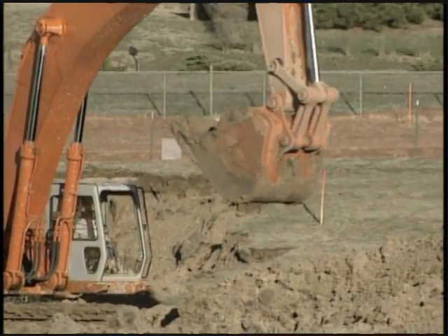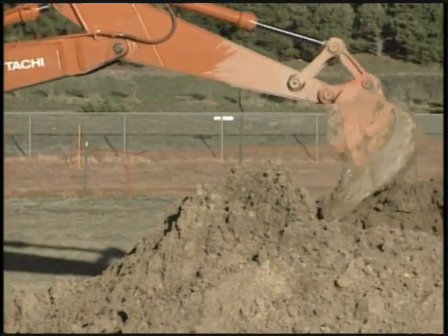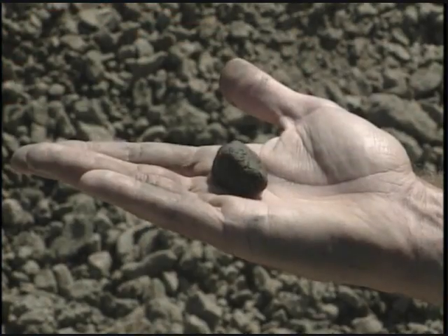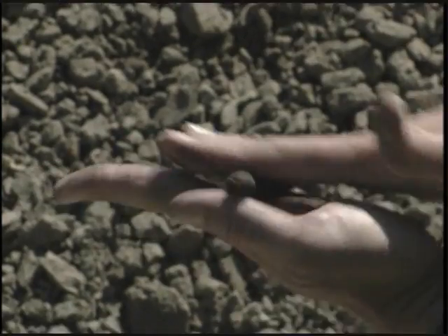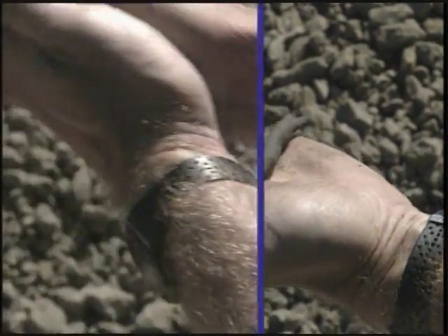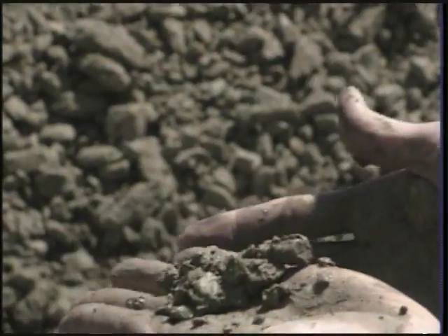There are a number of lab and field tests that can be conducted to determine the type and stability of soil. For example, a plasticity test is conducted by taking a wet sample of soil and trying to roll it into a thin thread without it crumbling. Cohesive soil can be rolled into a thread successfully, and granular cannot.